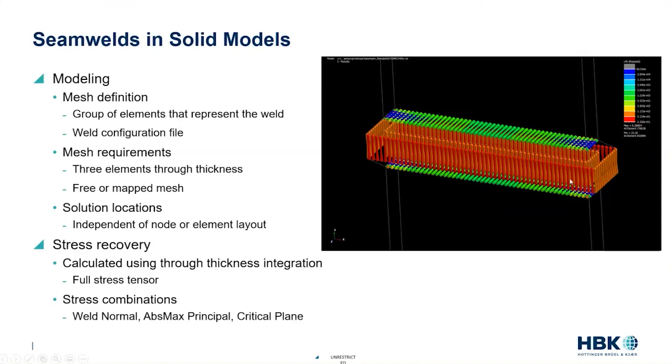These all basically use a structural stress, but it's going to be a different structural stress approach than the shells to make it easier to mesh in solids. Again, the meshing is pretty straightforward. You can be a mapped mesh, you can be a free mesh, you can be hexes, tetras. In general, this approach isn't tied to any particular node or element configuration. These are all basically just points on the part geometry, and it's independent of the actual mesh that's been put there. And so we're going to look at the structural stress recovery approach here, which is through thickness integration. And again, compare it to the benefits we see coming out of the nodal force and moment structural stress in shells.